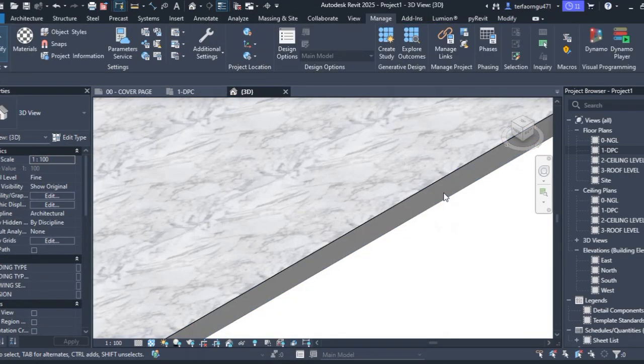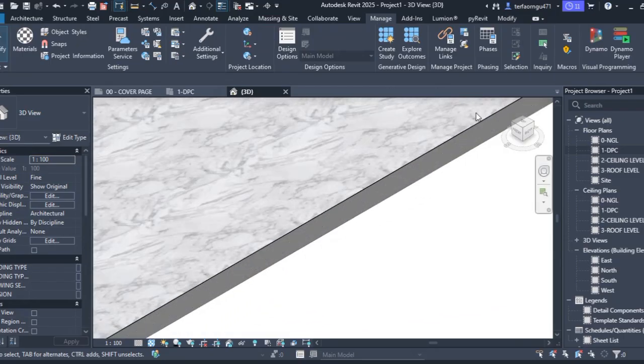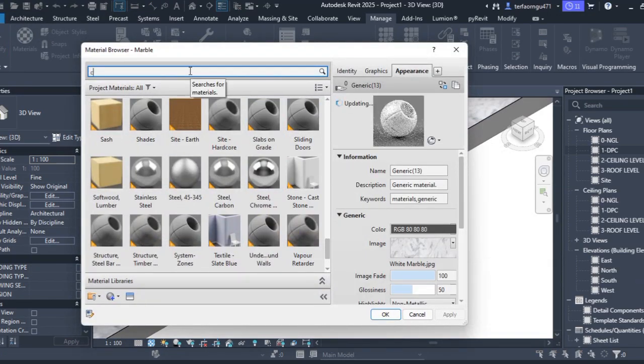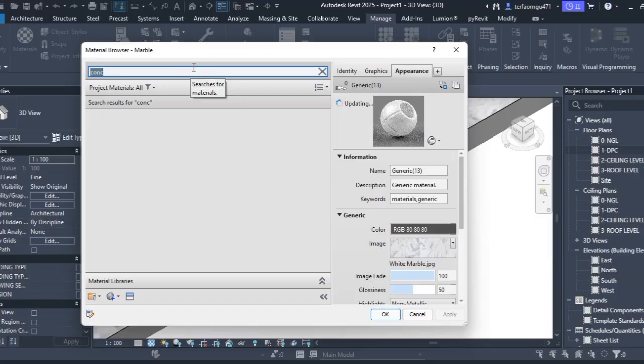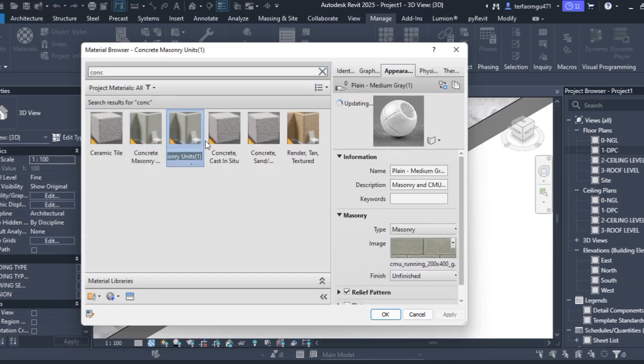So you can also decide to apply a different material to this part of the work. So let's say I want to apply like a concrete material here. So let me show you how to bring out a material from the assets browser into Revit. What I need to do is to go here, create, go to materials, and then let's say there is always a concrete material in this particular template that I'm using. So I have quite a whole lot of them. So let me use the concrete mainstream. I'm going to duplicate it, and then I'll call this concrete.